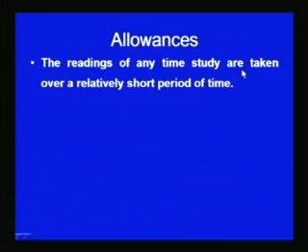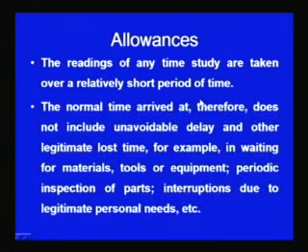We can see why allowances are given from the fact that when a time study is conducted, it is normally conducted for a very short period of time, and the normal time arrived at therefore does not include unavoidable delays and other legitimate time lost, for example, in waiting for material, tools, equipment, periodic inspection of the parts and interruptions due to legitimate personal needs.